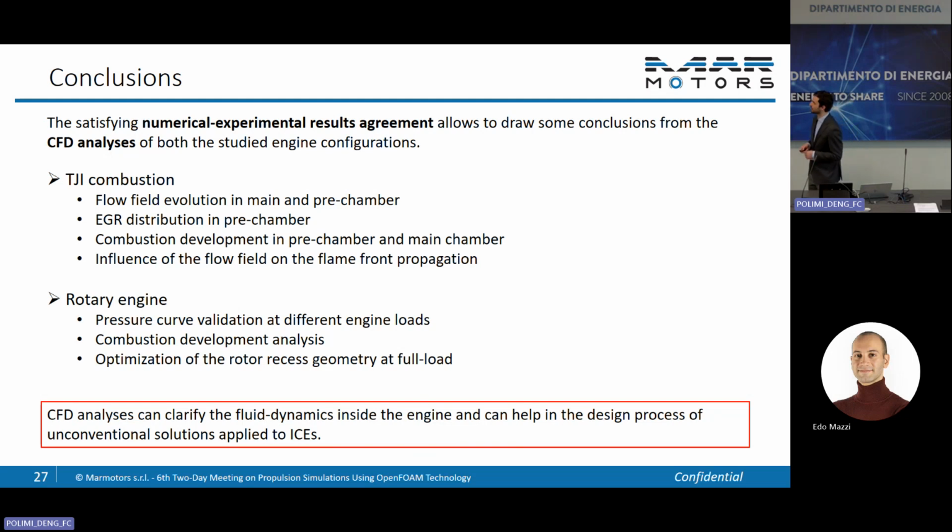And going to the rotary engine, thanks to the agreement of the pressure curve at different engine loads, we had the possibility to analyze the combustion developments inside a quite different shape of combustion chamber with respect to a normal reciprocating engine. And also we had the possibility to optimize the rotor recess in order to gain some performance before obviously machining it.